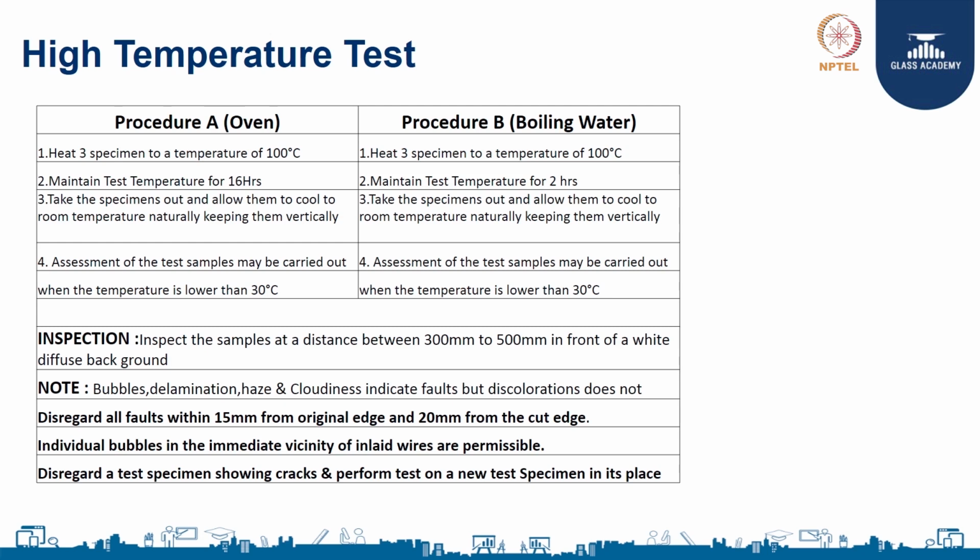For the boiling water, heat the 3 specimens to a temperature of 100 degrees. First, as I told earlier, we have to keep them at 60 degrees centigrade, then you have to transfer them to water at 100 degrees centigrade. Maintain the test temperature for 2 hours. Similarly, take the specimens out and allow them to cool at room temperature naturally, keeping them vertical.